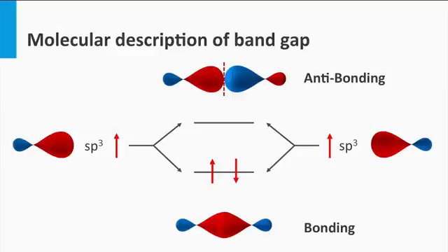In week 2 we have discussed that 2 individual sp3 hybrid orbitals of a silicon atom can make an anti-bonding and a bonding state. The same is valid for the 2 pz orbitals, making a molecular pi orbital. They make a bonding and anti-bonding pi state. Therefore, conjugated molecules can have similar properties as semiconductor materials. Most electrons are at room temperature in the bonding state, also referred to as the highest occupied molecular orbital, HOMO. The anti-bonding states can be considered as the lowest unoccupied molecular orbital, the LUMO.